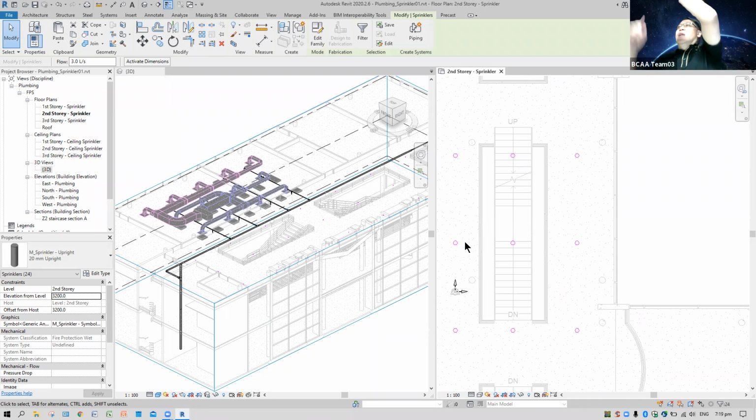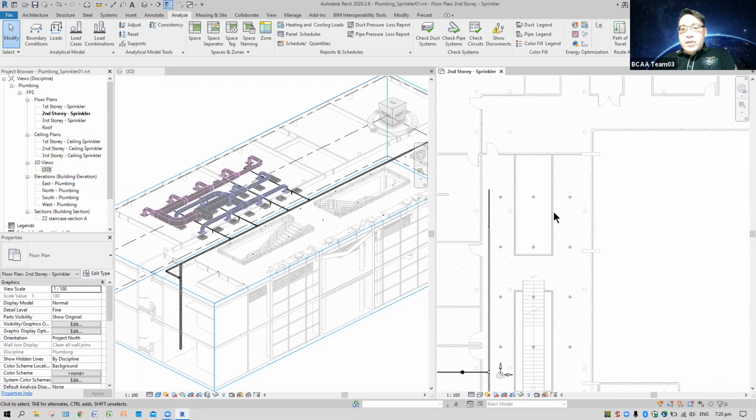Because from ceiling coming down to the sprinkler is like what people told me, 200 to 300, so they can actually wet the slab. Because your 3.8 minus your slab is around 3.5 something. So I give this 3.2 plus a sprinkler, maybe less than 300 or 300 plus. So I think it should be more than enough. Okay, now I try one more time to get a connection.